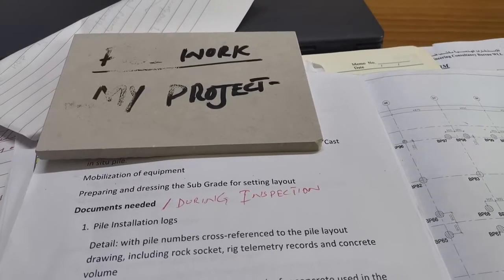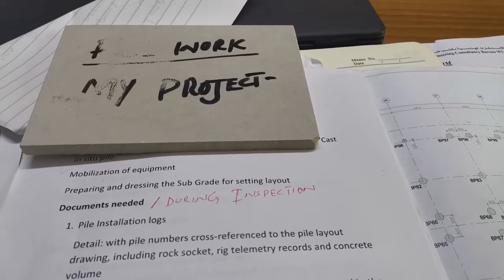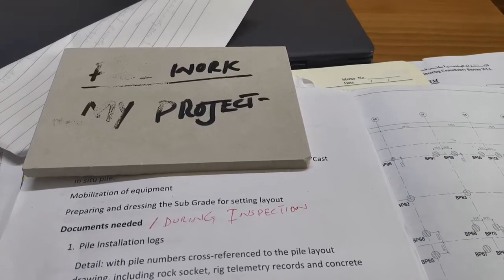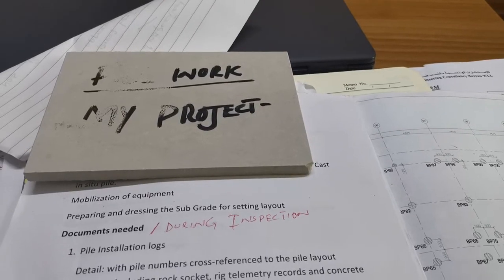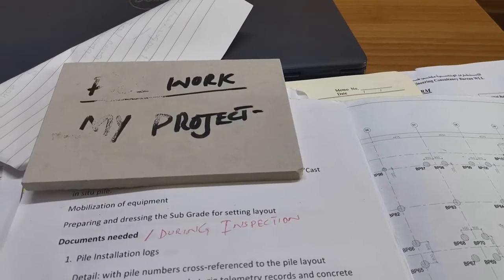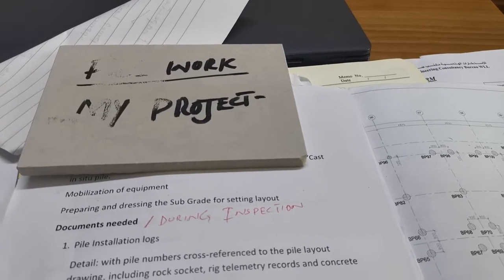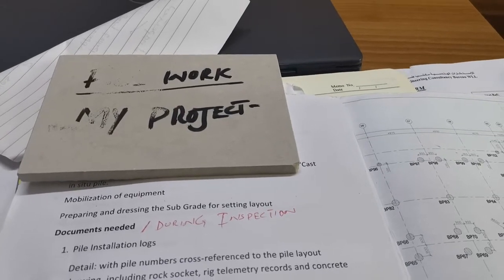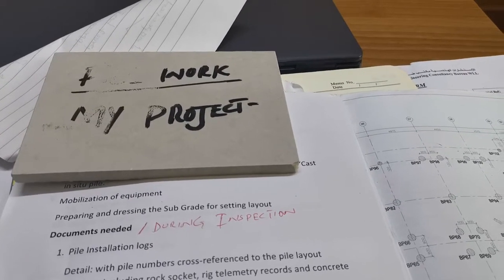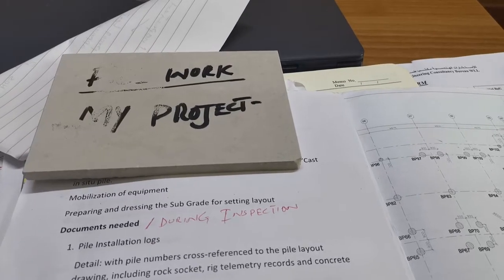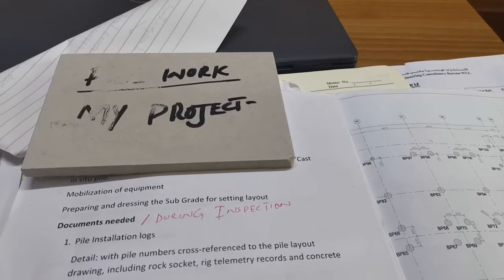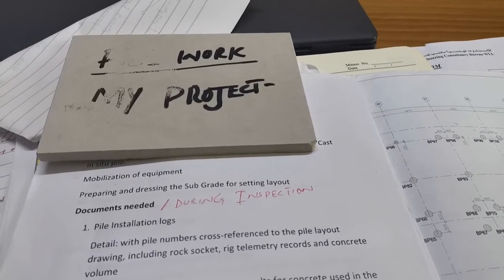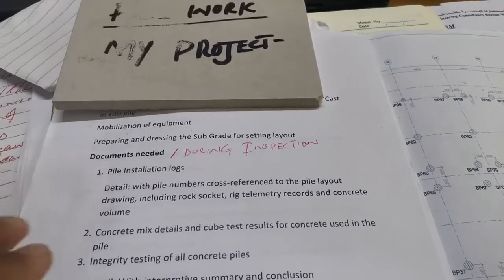Basically, I am telling you about the cast in situ piles. What is the difference between cast in situ and precast? The construction which we are doing on the site means live. All the things we are preparing on site, maybe steel we are getting from the factory according to the drawing, and we are installing the cage, doing the boring and the cage on site, and concreting. That is called cast in situ. If we are taking all these things ready-made from the factory, means piles or roofs, that is called precast.